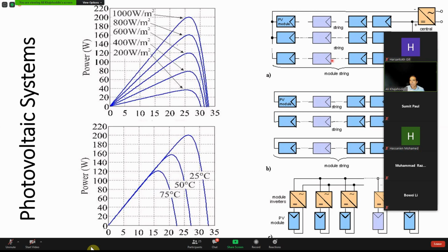So that's why this centralized inverter topology is not very good. To solve this, they can have inverters for each string. So now, if one of them is having a problem, this will try to optimize the voltage here, whatever is left. But over there, this inverter has no access to voltage and current of this individual string.